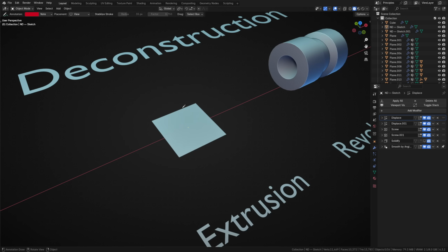Unextruding this cube is not the same as squashing it by scaling it non-uniformly along one axis. Of course, scaling any shape on one axis to 0 will leave it flat, but that's not the same as unextruding it. A good way to think about it is that extrusion uses guardrails. This cube's 4 perimeter edges guide the extrusion upwards.